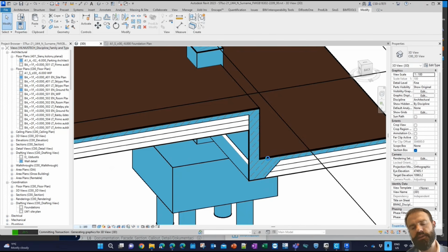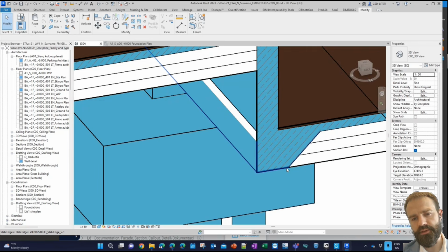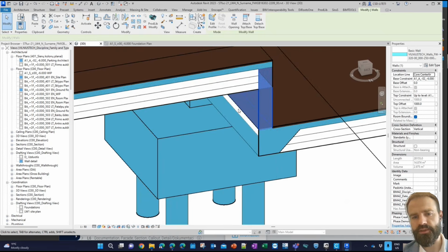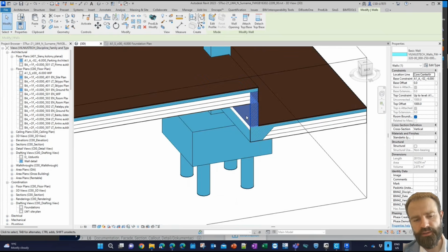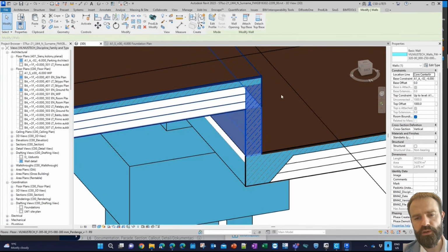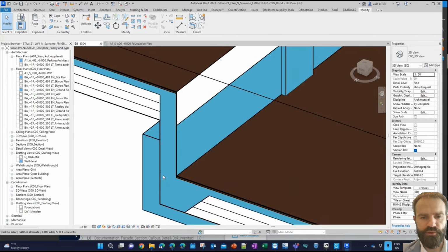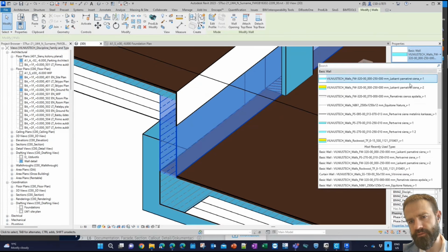Of course, from the construction part, if we want to use insulation or other layers, I should put insulation below my slab edge and also put insulation on the sides of this wall so I can protect it from the ground and from water effect on my construction and so on. So additional modeling should be done. Maybe I need to create a different wall type to solve this situation. But for this example, I wanted to show the slab edge and how this wall works.